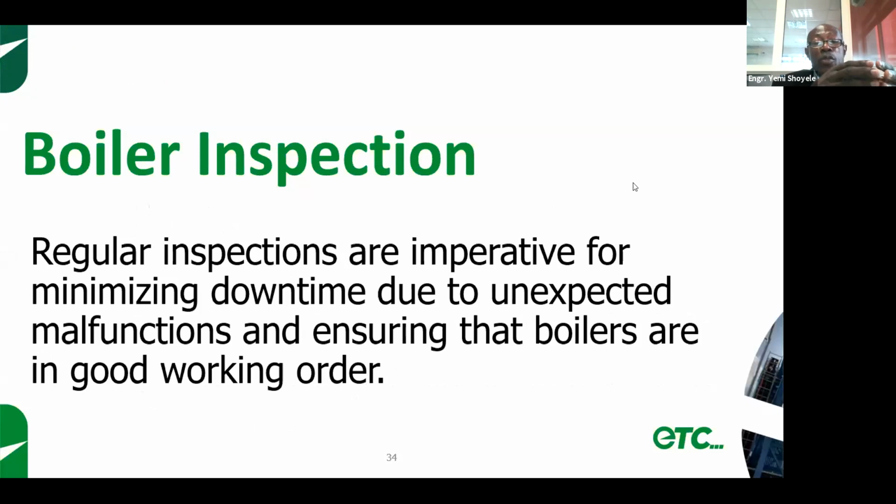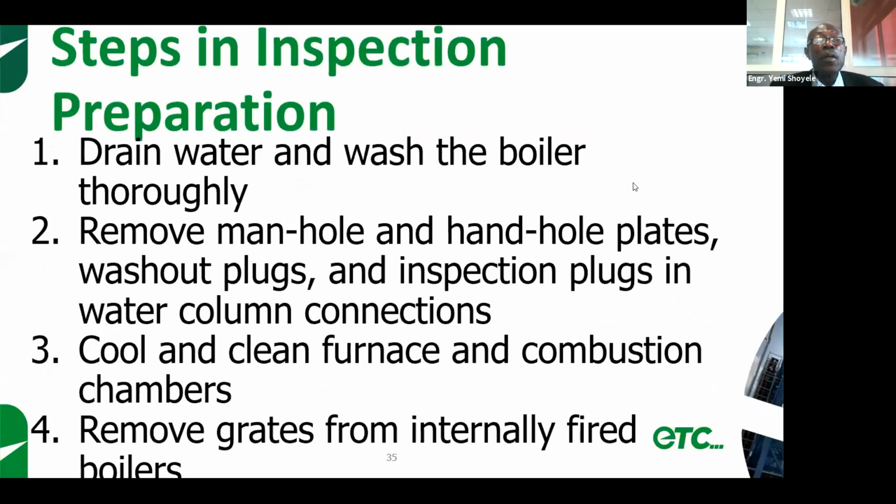So regular boiler inspections are imperative for minimizing downtime due to unexpected malfunctions and ensuring that boilers are in good working order. Now, you've also got to prepare your boiler for inspections at the end of the year. There is a mandatory insurance inspection that you must carry out annually on your boilers. And I hope everybody is adhering strictly to that, not just because of the value of the boiler, but because of the consequences of a boiler failure, like boiler explosion. So an inspector comes in, or you will invite the inspector to come in once a year through your insurance company. These are things that you need to do before the inspector arrives.